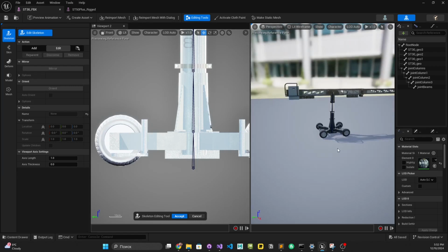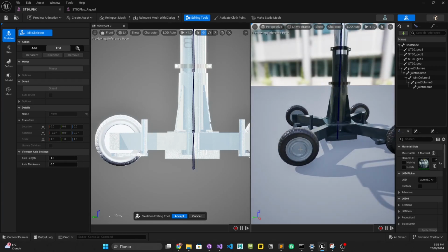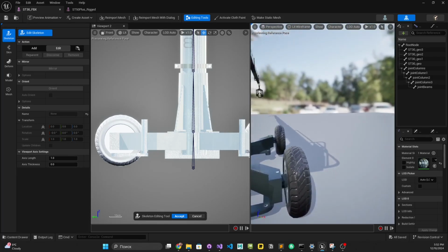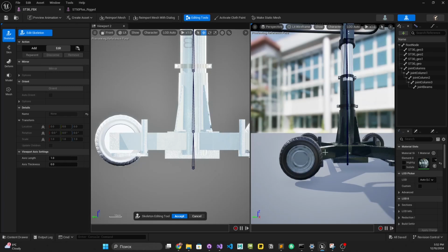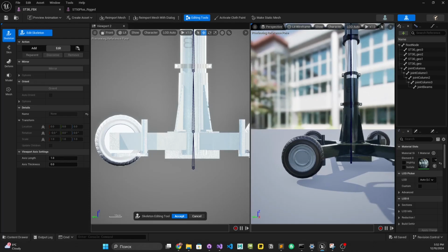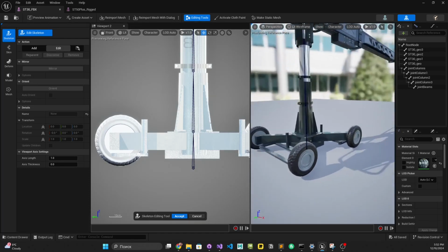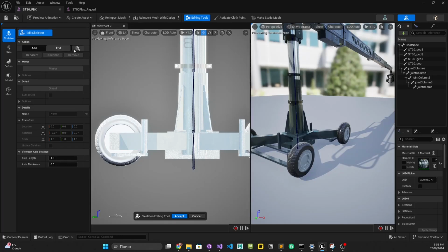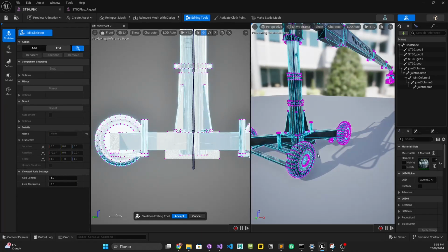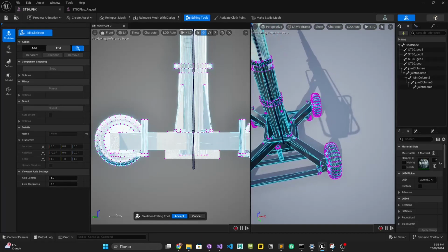And in that case, I would imagine there has to be a joint like a pivot point so that we have the center of rotation and the joint. Rotation of a joint will cause the whole geometry, the whole shape, to be rotated. So there has to be some positioning just inside the shape in the absolute center. In that case, the rotation will not cause any offsetting or vibration. And in order to do that, in the edit skeleton, we have this mode of select vertices, edges or triangles to place bone. I think that's a perfect fit for our need.